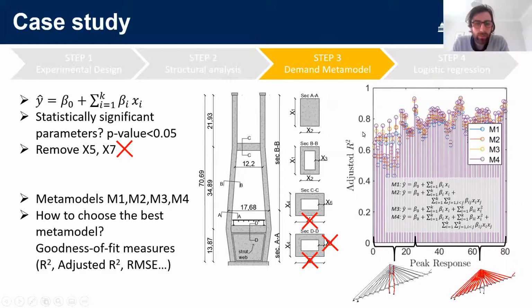Okay, that's great. And for the Metamodels in your final analysis, did you use an ensemble, or did you just pick the best one? And also, did you do anything to avoid overfitting? Maybe that wasn't a problem. Yeah, it's also a point that comes up when we select the Metamodel. For example, if I only consider 80 sample points, which means I just run 80 analyses, the Metamodel M4 had a problem of overfitting, because the number of parameters to be estimated would be really large.